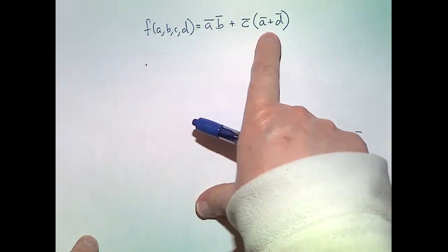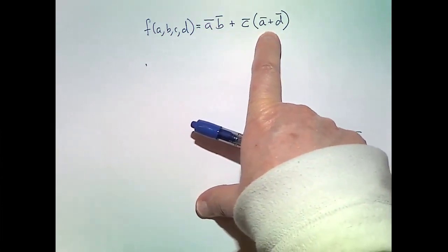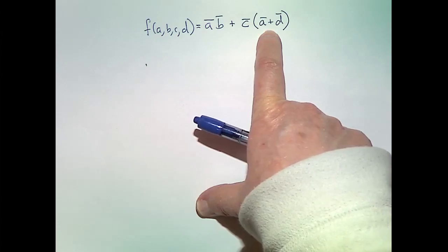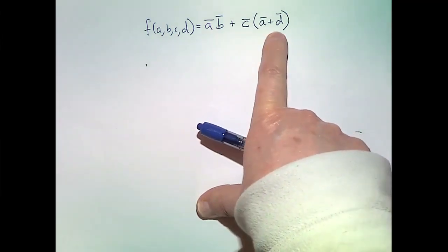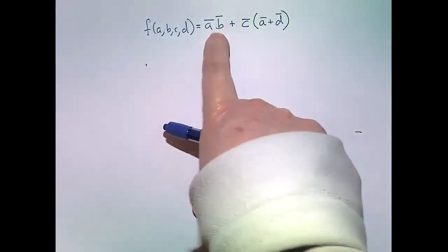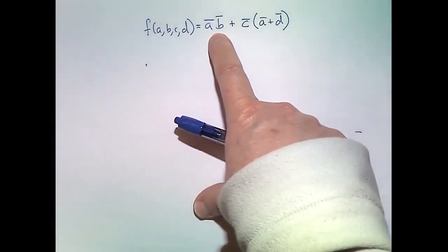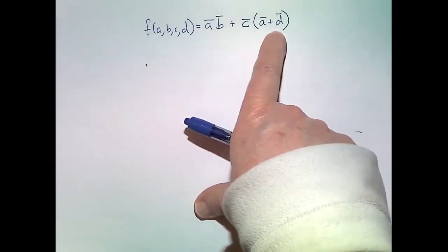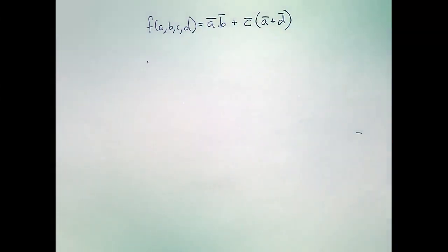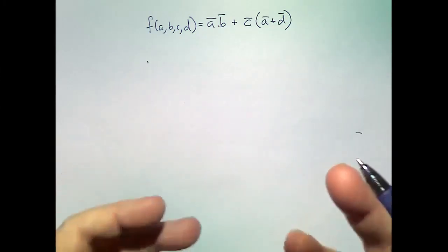So whenever this expression is 1, we want to pull up the output. We want the output to be 1. So we need to make a network that connects the output to the power supply when this expression is supposed to be 1. And we have to build it out of PMOS.